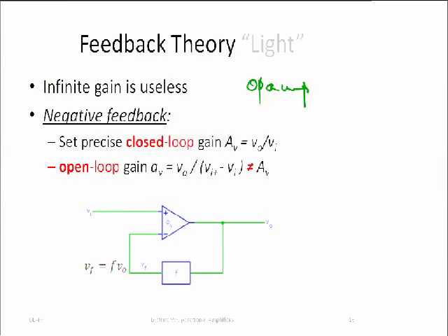And this op-amp component we can use. It's very interesting how it's made, and you'll learn that in EE 140, should you take that course. But anyway, this operational amplifier is very convenient to build all sorts of amplifiers. It has one very strange property, and that is the gain is extremely high. In fact, it's almost infinite. For all practical purposes, in most circuits, you can assume that the gain of an operational amplifier is infinite.